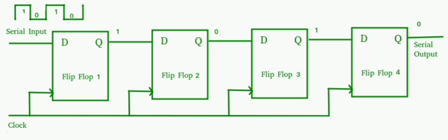EPROM stands for erasable programmable read-only memory. The presence or absence of a charge in the floating gate of a double polygate MOSFET determines the logic state. EEPROM stands for electrically erasable PROM. Programming and erasing in EEPROM is achieved by forcing the channel current to flow between the gate and substrate.